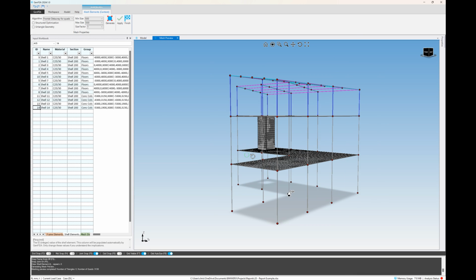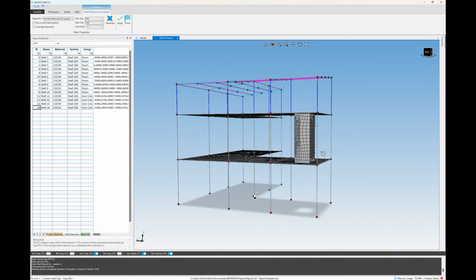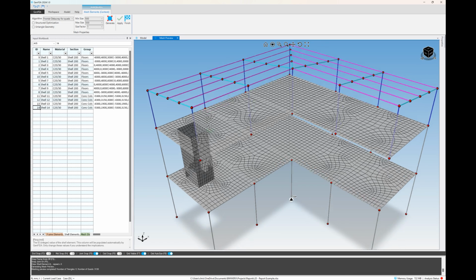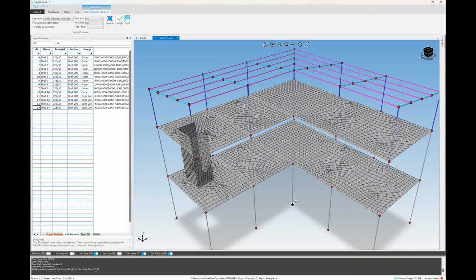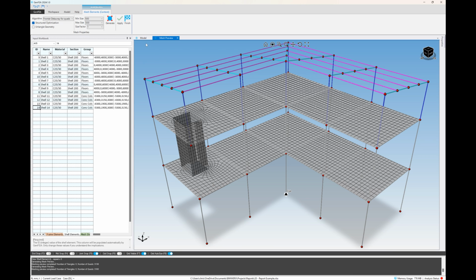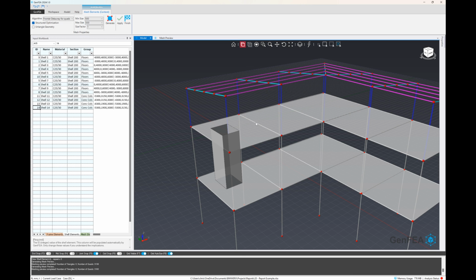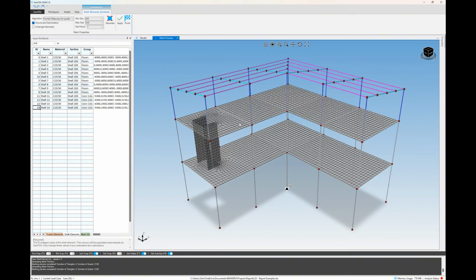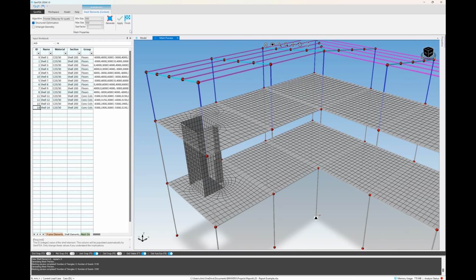default settings. And what this is going to do is give us a preview of the mesh that is going to be generated. We can see this is a pretty decent quality quad mesh, but not exactly structured. So we can use the structured optimization button, hit generate again, and without bringing the elements back into the model and splitting or discretizing the connected elements, we can first have a preview on what that result is going to look like.